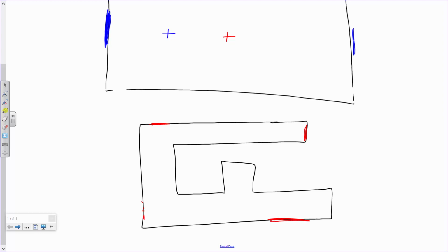You might have an instance where the center of mass is right there and the center of rigidity is up here. So regardless of where the wind hits the building, it's going to want to twist it. Does that make sense? Everybody okay with that? I'm showing you that because I want you to understand what you're about to see in a quick second. All right?